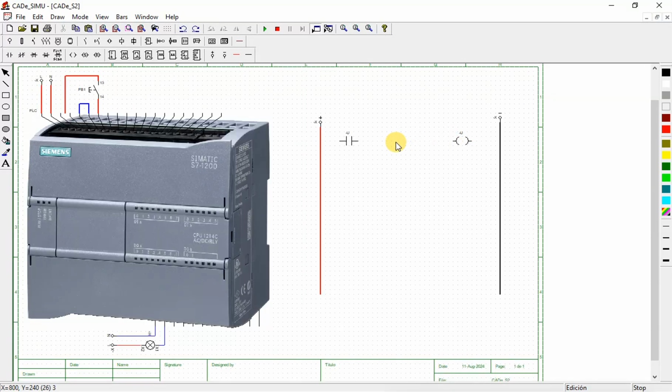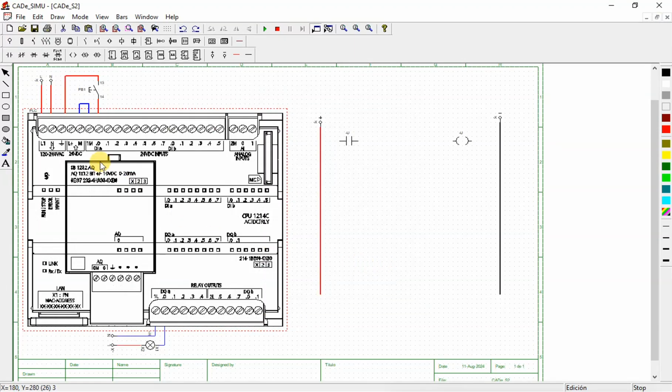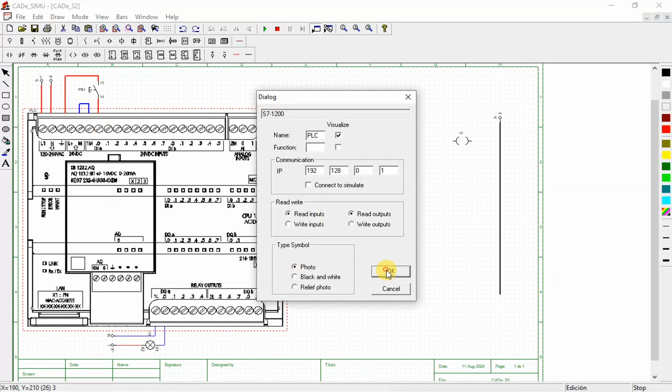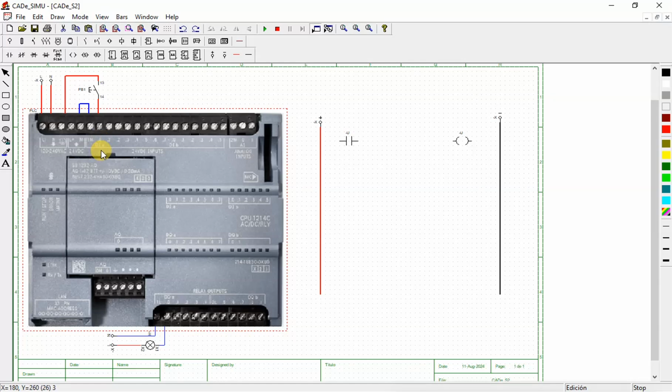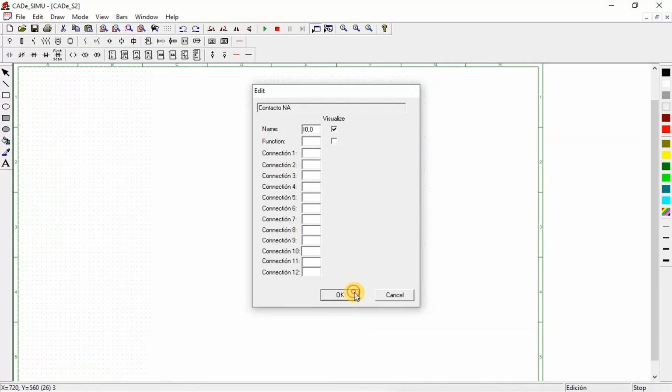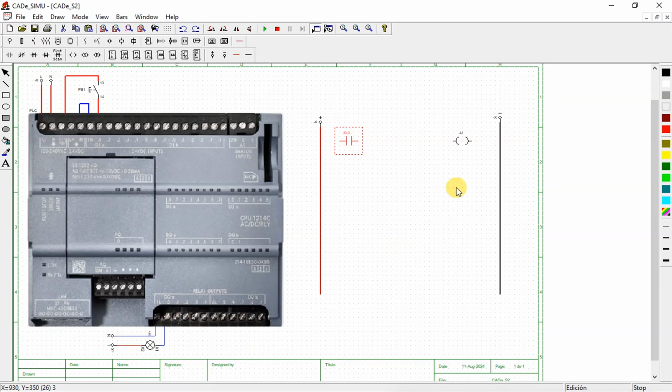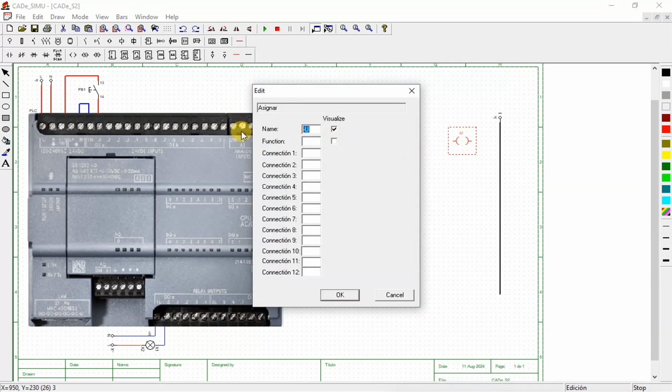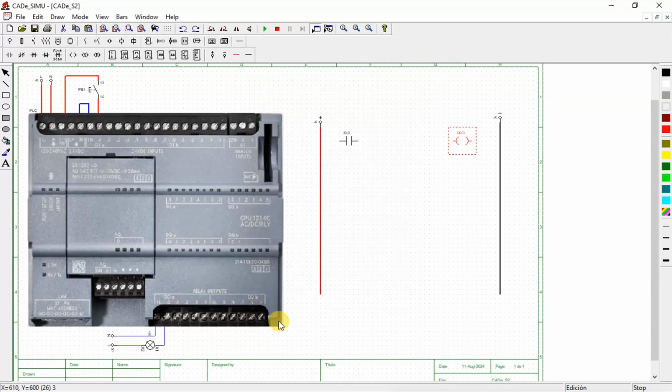Now what helps these contacts here to communicate with the PLC is what we call the addressing. When we look at this PLC here, our push button, the input here, we have given a digital pin, that is input, it is I. So here we have to address I, capital. Then it is the first section, which is 0.0, that is our input. Then the output we addressed, it is Q 0.0. That was the output pin where we put our lamp.